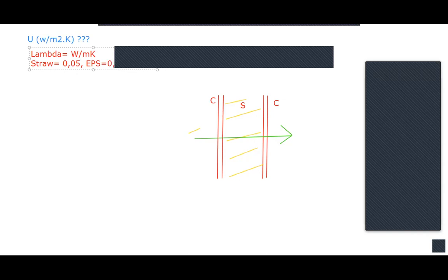For some other insulating materials, let's say Steico protect, it has for example 0.055, so it's in the same range, very similar to conventional insulating material. So wow, this is a huge opportunity to use straw bales when you have right away very good insulating material. So we have our lambda value for straw.